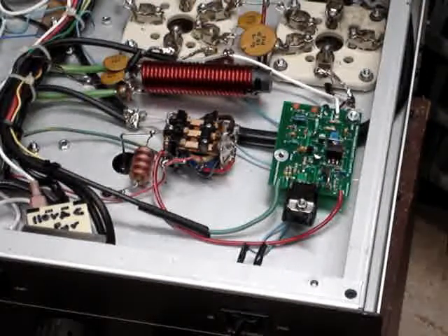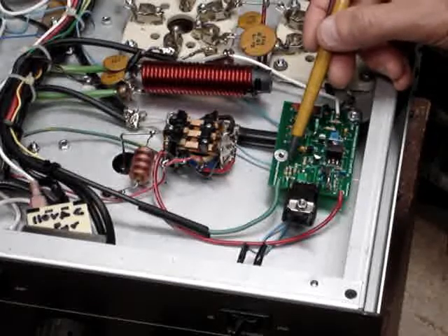There is one other thing I would like to point out about setting up the bias. Remember, I said that we need to have some minimum current. In this particular amplifier, we chose 7 milliamps, and we'll discuss later why that was a good number for this particular combination. How we set that current, though, is this resistor here.